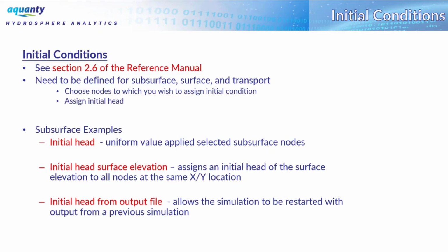Usually what you'll do at the beginning of a new project is you'll start the model fully saturated, and you can run it for an extended period of time using just net precipitation as the main boundary condition. Eventually the model will sort of drain to something that is representative of a long-term average climate hydrological condition for your model.